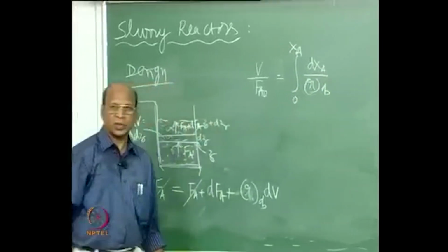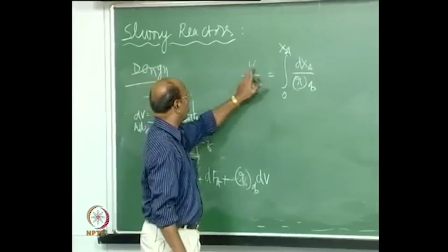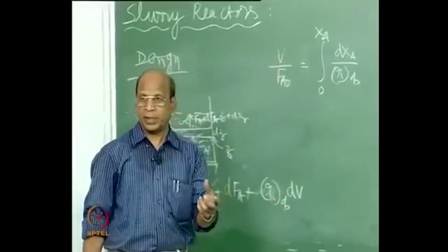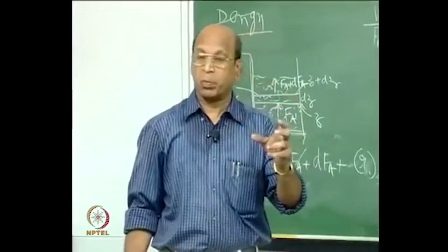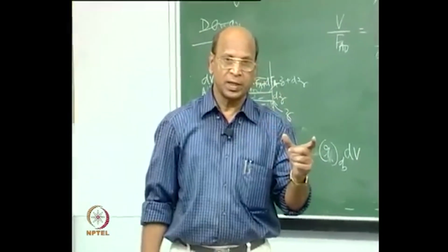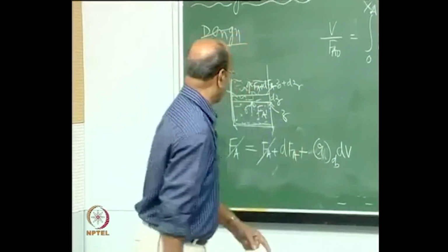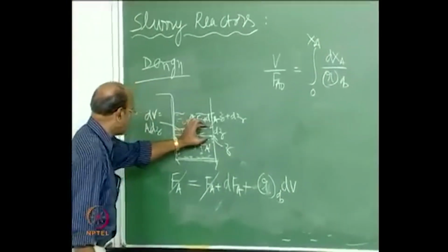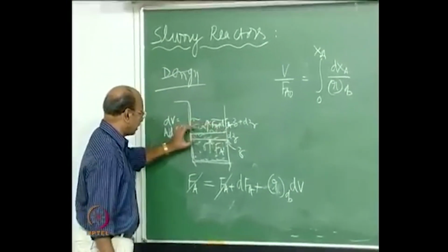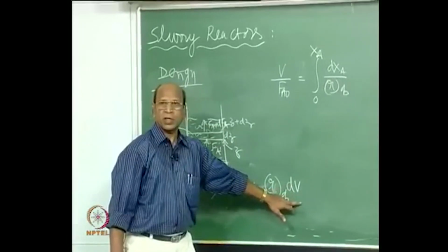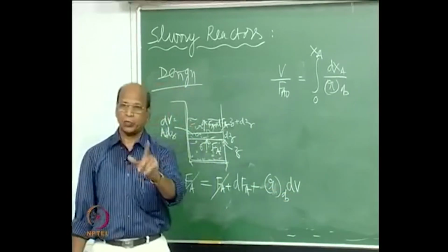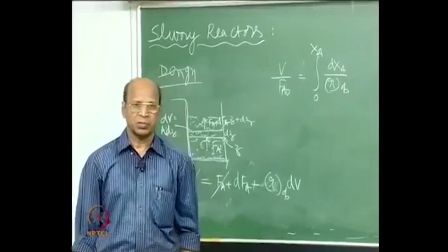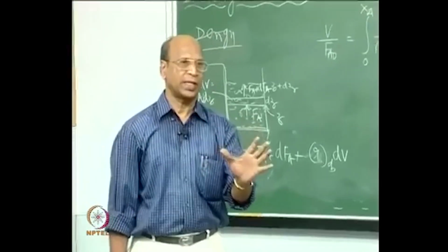that is the one. So now this volume is not simple volume in meter cube, but the volume of bubble free liquid. Why? Because here what we have used is volume of bubble free liquid. This balance you are writing must be only for bubble free liquid. That is the only thing you have to take care of in heterogeneous systems.